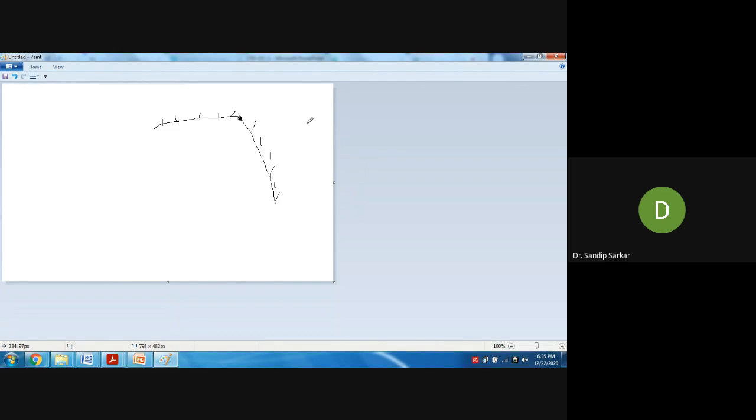Then what will be the boundary condition? Because for this wall you may have a vorticity boundary condition similar to the method that we have already discussed in the class. You may obtain a boundary condition for the vorticity at this wall. Similarly, for this wall also you can obtain a boundary condition for the vorticity. But what will be the boundary condition of vorticity at this corner?